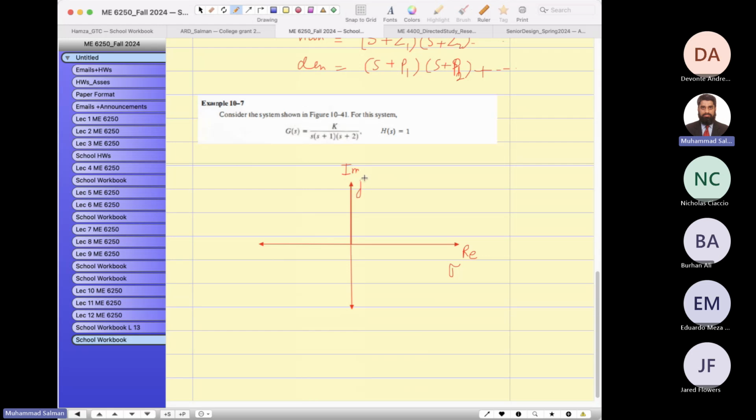J omega, I would say j omega sub d, because this is the damped natural frequency. So s equals sigma plus j omega. Now, how will you locate these poles onto this Laplace plane? The first factor is s equal to 0, the second factor s plus 1 equal to 0, that means s is equal to -1. The third factor is s plus 2 equal to 0, so s is equal to -2.